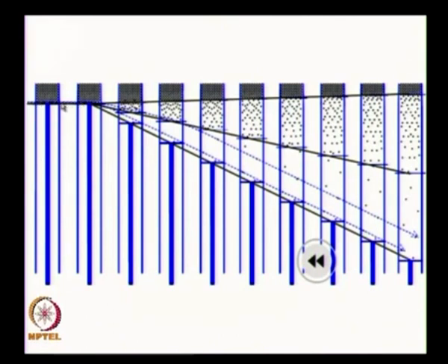The stream tube is really small in area in a cross section here, and after the expansion they have become really wide, basically telling that the flow has expanded. Okay. That is one way of looking at it. Another way of looking at it is during the expansion fan the stream tube area is changing, okay, and the stream tube area is expanding. If you look at it inside the expansion fan, the stream tube area is increasing along the flow direction.